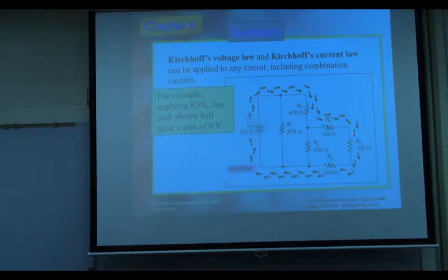Then plus this one, the voltage drop across R5, which is from here. This one minus this is positive. Then plus this one minus this, which is the drop on R6 in this way. Right? Then nothing else. So all these 1, 2, 3, 4, 5 values, the voltage drops, add up together equal to 0. So that is the KVL for this closed loop.